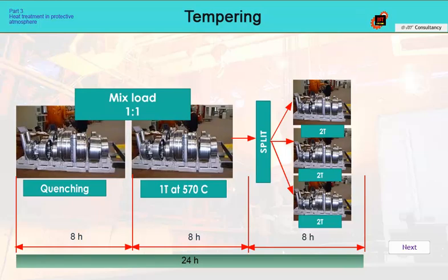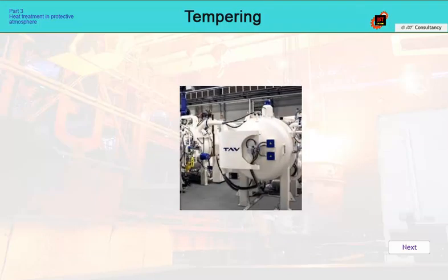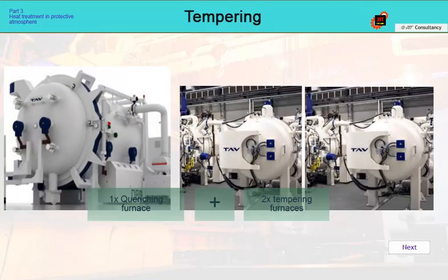This is very important. However, the condition is that the hardening and the first tempering take place in a furnace of the same dimensions. It follows that each hardening furnace should have at least one tempering furnace of the same size, but in practice, a ratio of 1 to 2 can be considered more advantageous. That is, at least 2 tempering furnaces should be available for one hardening furnace. This is the only way to ensure optimal service for the customer in terms of time, quality, and price.